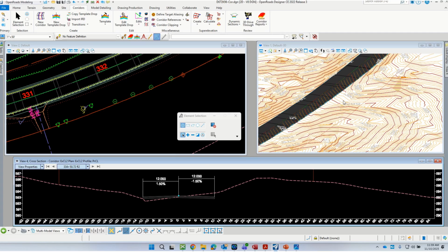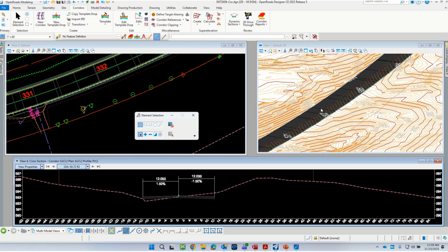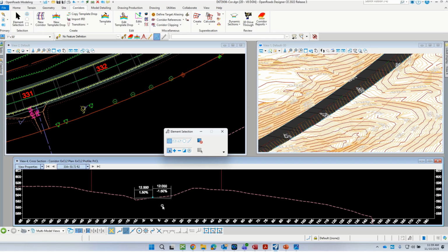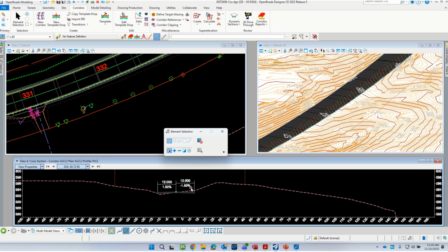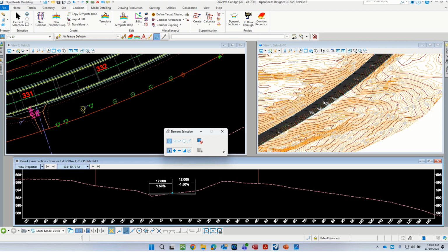So I think what we will do next, as we're developing this template, and we wouldn't necessarily have had to do this in this particular order, but because the cross slope is so steep at 6%, why don't we go ahead and calculate our super elevation and apply that super elevation to this corridor, so that as we develop the remainder of the template, it'll look a little bit more like the final product anyway.